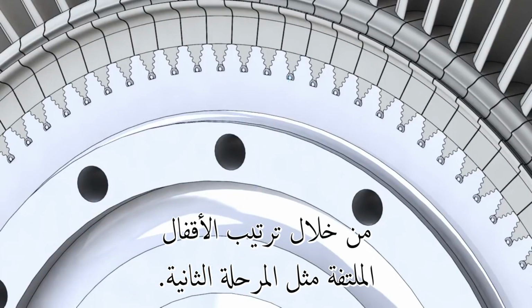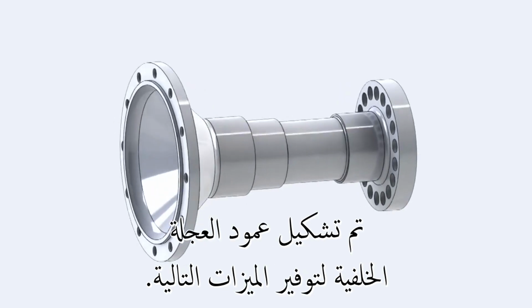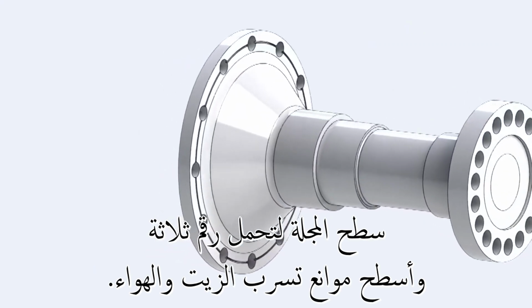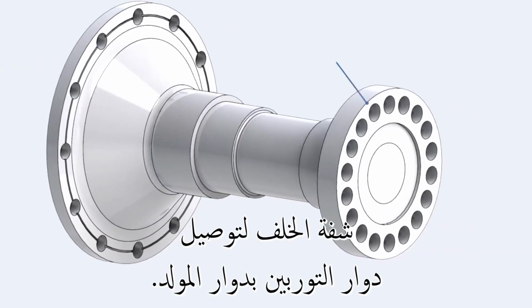like the second stage. The aft wheel shaft is machined to provide the following features: journal surface for bearing number 3 and surfaces for oil and air seals, aft balancing groove, aft flange to connect the turbine rotor to the generator rotor.